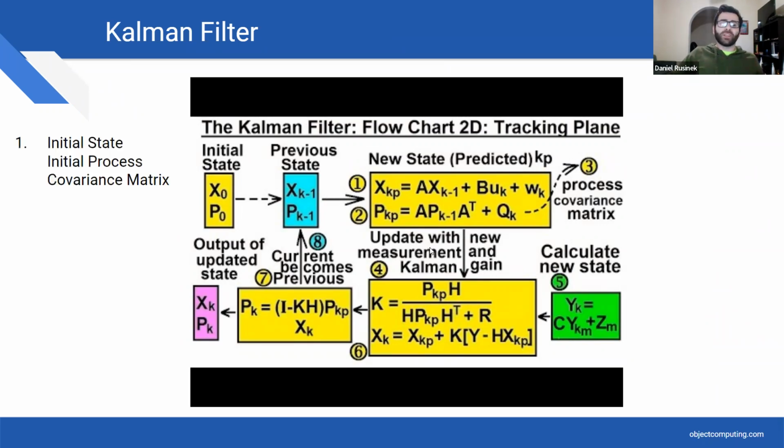But the process pretty much goes where you have an original error estimate and you kind of just guess on that. And you calculate your error in your data. So you calculate a new estimate, then you add some noise to it. You look at how much uncertainty you have, you pass it through your Kalman gain.